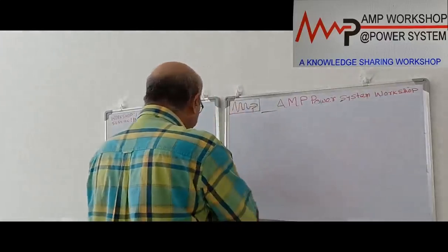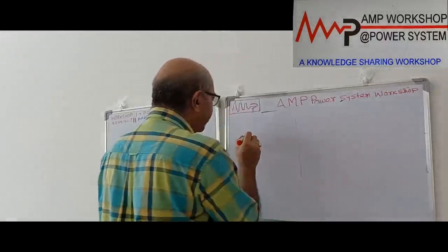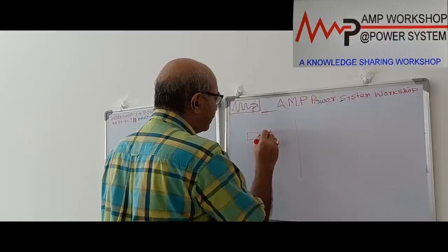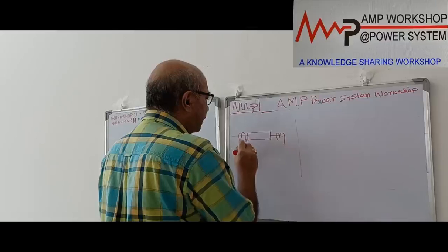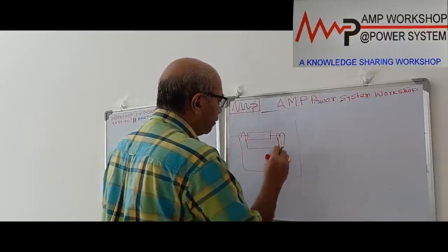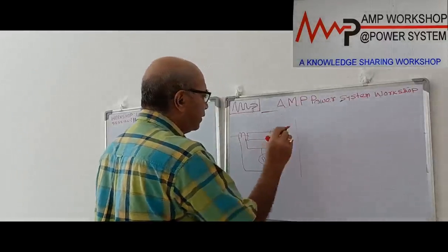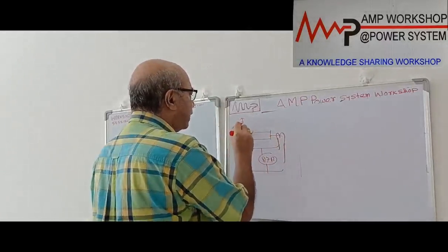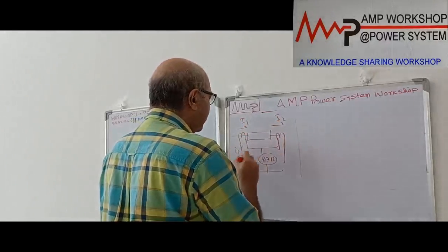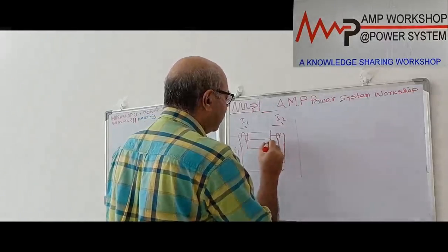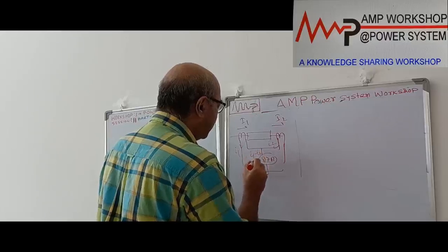So in the same way, this is how we do the bias characteristics. Our scheme is the same. This is our busbar. The CT is over here. This is the incoming side. This is a busbar differential relay located over here, 87B. Yes, this is the scheme. And the primary current flowing is I1. This is I2. The corresponding secondary current is I1, this is the secondary current I2, and the differential current is I1 minus I2, that is equal to ID.